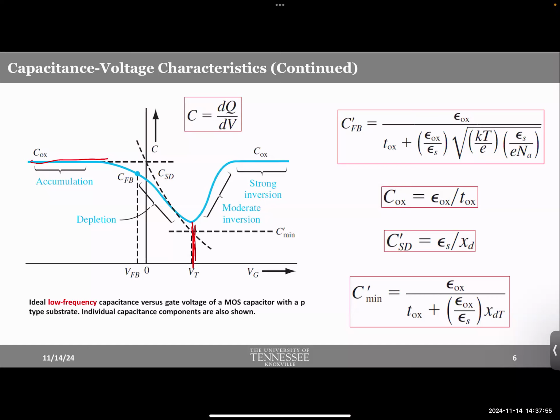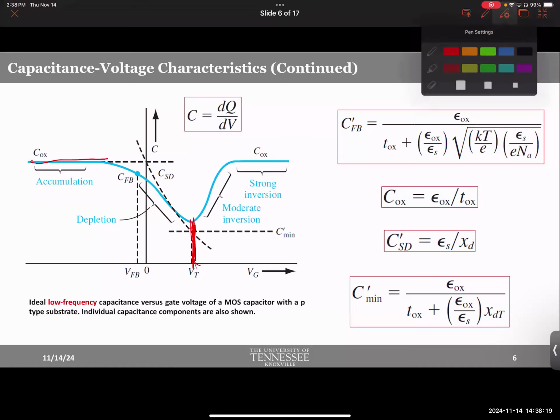You do the math when you're just developing the device. But after you're done developing it, it is a matured device. You're just optimizing it. You basically do experiments and figure out the threshold voltage like this. Measure CV, and the minimum point will tell you where the threshold voltage is. Interesting, is it not? So wouldn't you do this type of characterization in the lab? This is one of the reasons why I do CV characterization.